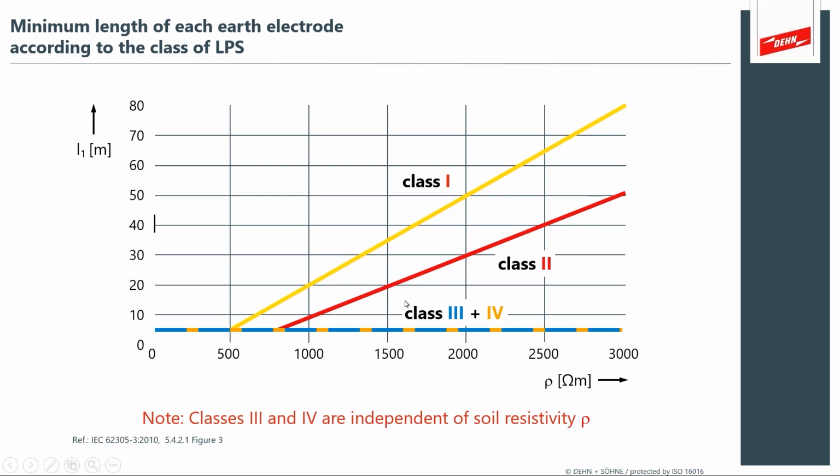But as you go into the more stringent lightning protection class, when you get into these high soil resistivities above, say, 700 ohm-centimeters, it allows you to then evaluate and install a deeper and or longer earth electrode system to get you to the same equivalent connection to the soil.